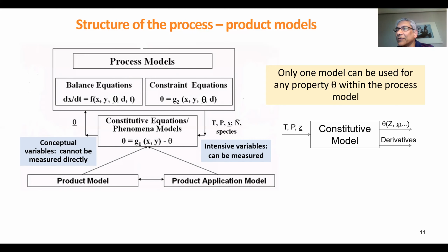If somebody is developing or using surrogate models these days, not using the derivatives would mean that the thermodynamic model or the surrogate model may not be thermodynamically consistent, because those derivatives are telling us whether the thermodynamic consistency conditions, like the Gibbs-Duhem conditions, are satisfied or not.